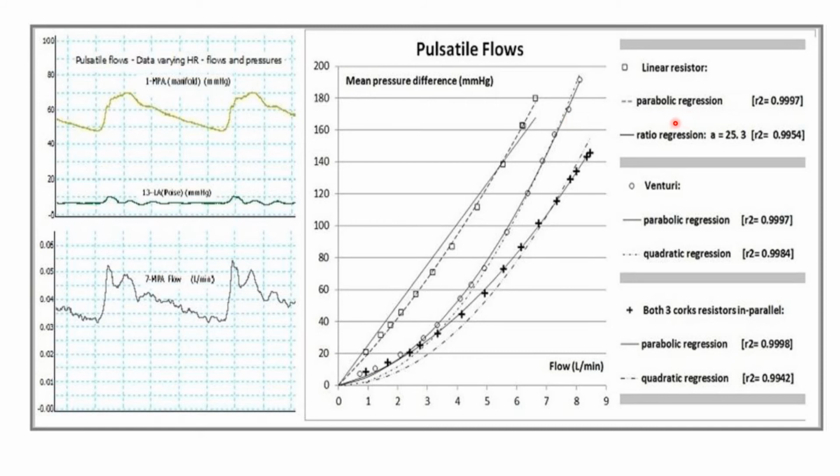And with that, I would use the parabolic regression. You see that those dots are the true data, and you see the parabolic fitting very well. And because it's a linear resistor, you use the linear regression, and it's not as perfect. Now, what I want to say here is a small, important detail for you maybe. In the beginning, you see this very straight, and after some point it starts to bend.